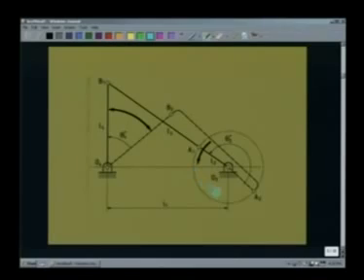As the crank O2A of this crank rocker mechanism rotates, there is another configuration where O2A2 and A2B2 again become collinear. The corresponding configuration of O4B, that is O4B2, is the other extreme position of the follower link, that is link 4. So, we are considering a crank rocker mechanism, and we see that as the follower goes from O4B2 to O4B1, during this movement the crank rotates from O2A2 to O2A1. That is, it moves through an angle theta 2 star.